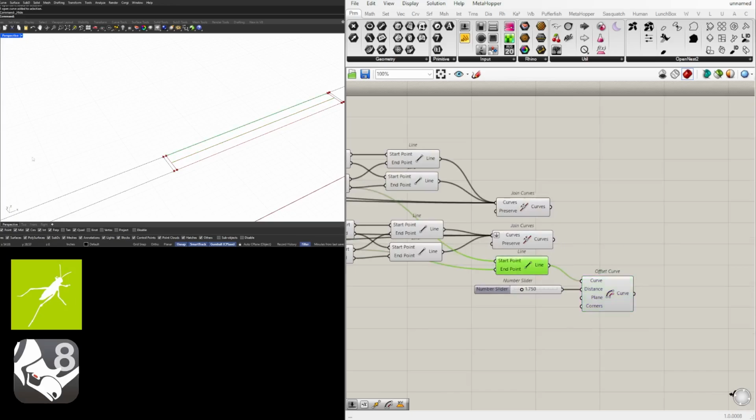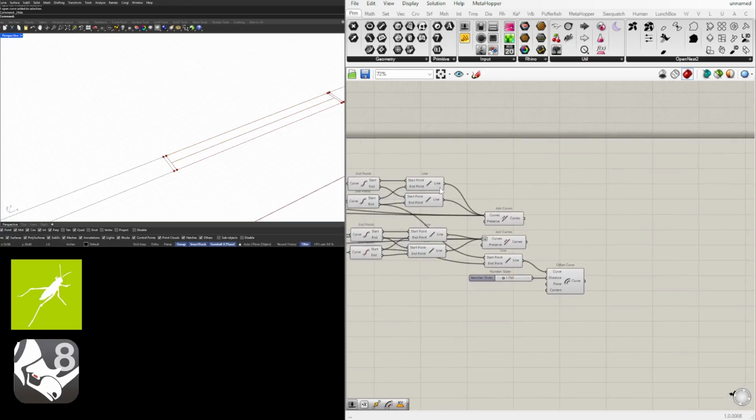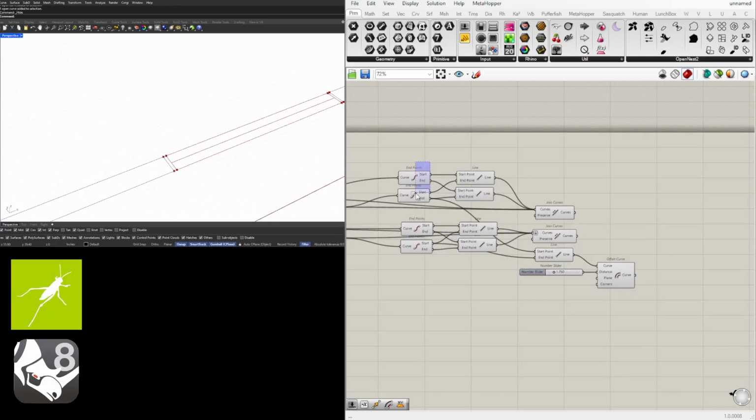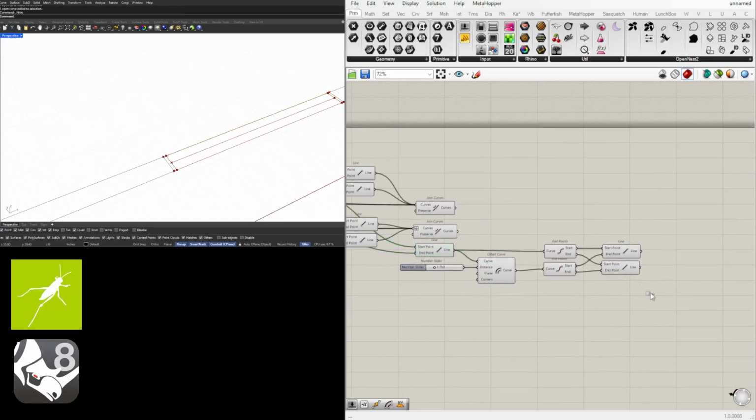And so we have the original line segment between those two. We have the door. And now we need to join those together using this same technique where we get the endpoints and the line segments. So we'll copy this over because what it does is create the endpoints for this line, the endpoints for this line, and create the two connecting line segments.